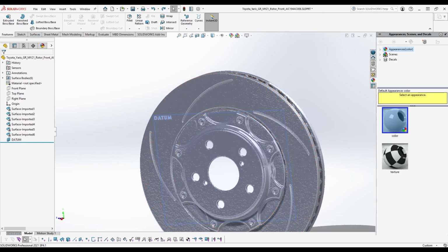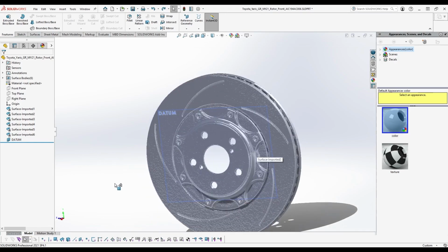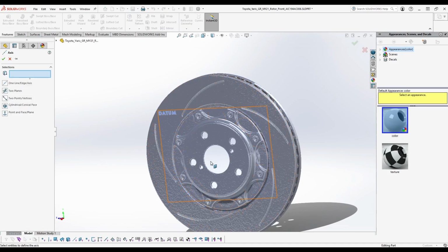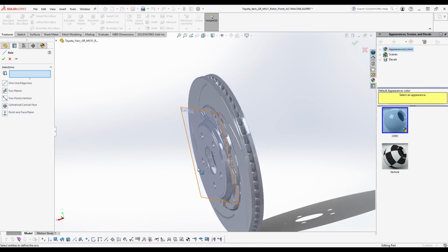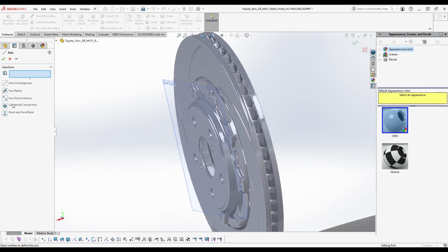But say from here, you can do plenty of things. We've made a plane, so we've worked with an STL, which is great. There's other things that you could do. You could do an axis. Now, say you want to do an axis about the center because you want to design the part and make sure that you know where its center is. You can actually go to make an axis based off of a cylindrical face and paint selected facets.